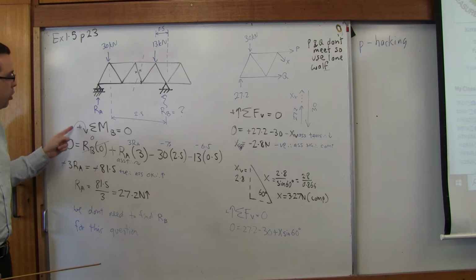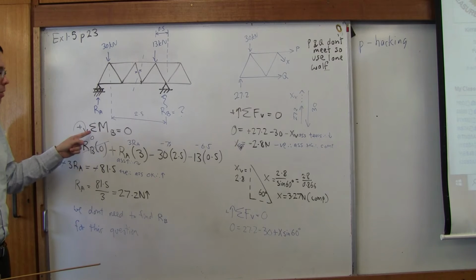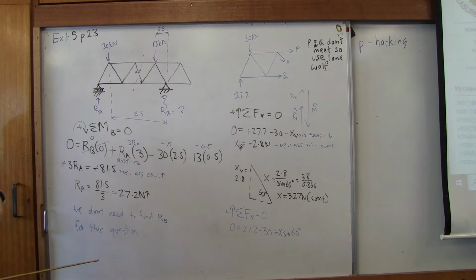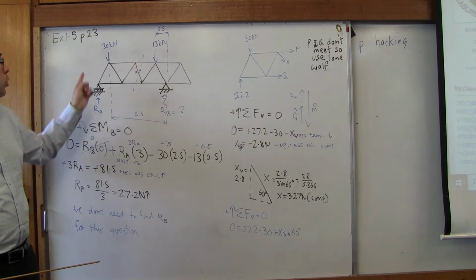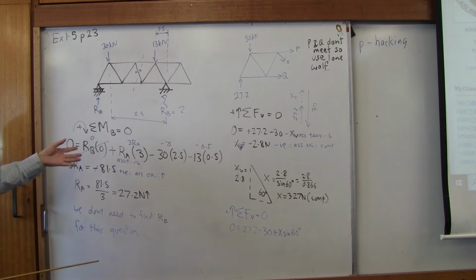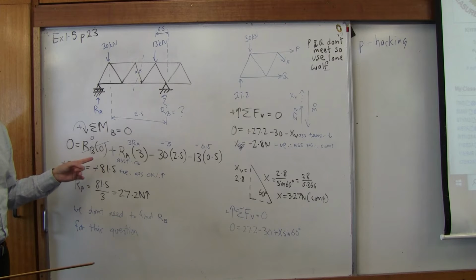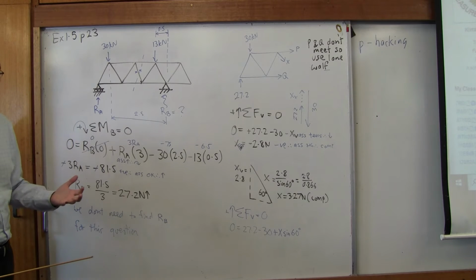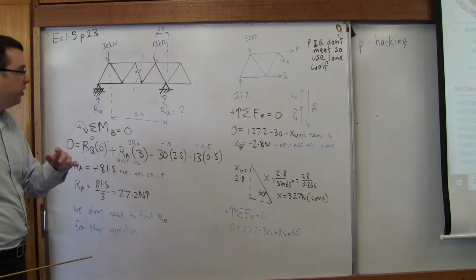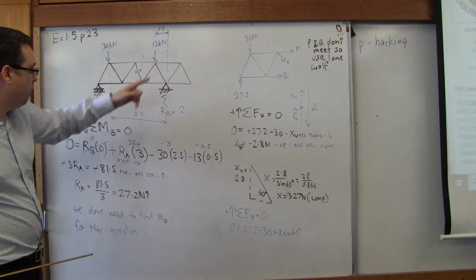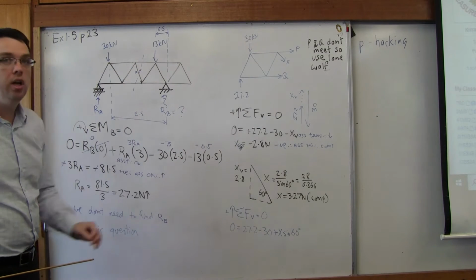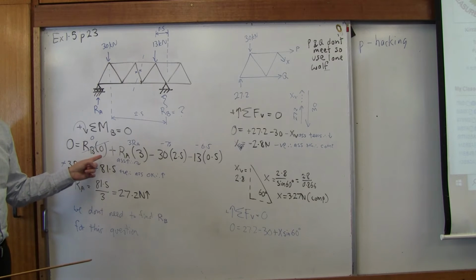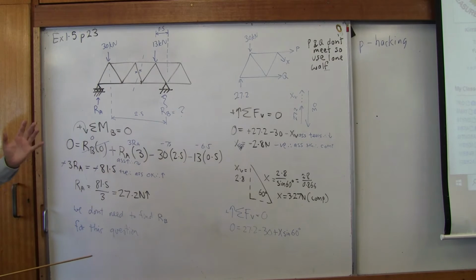Okay, so we're going to go through this equation. We've got the clockwise sum, that's a sigma, of moments measured from location B equals 0. How many forces do we have? We have 1, 2, 3, 4. Now often, textbooks will not include this first part because it's 0. They're like, we don't even care. But me, I like to explain why we're taking moments from point B and then to list out every force. Let's have a look. So we're going to say reaction B multiplied by 0 is 0. So I put a line through it to show we don't actually even need that.